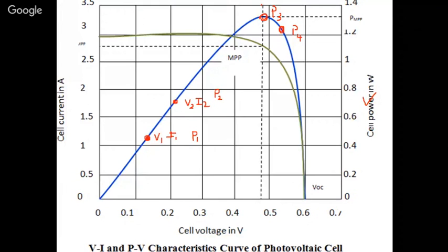I am telling you my PV is there and I am measuring. You will have a voltage sensor and a current sensor, and you measure it. You have some Hall effect sensors or potential dividers, something, and just measure it. But how will I disturb my system and change the operating point? So that I'll just show you.